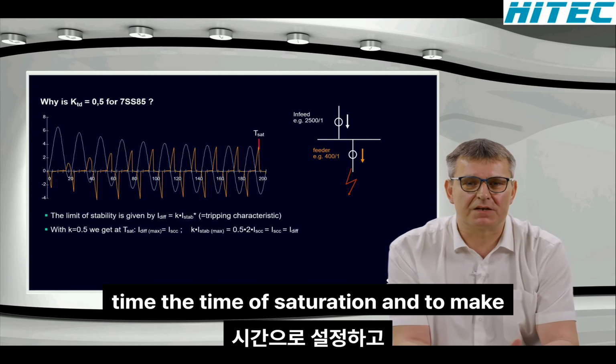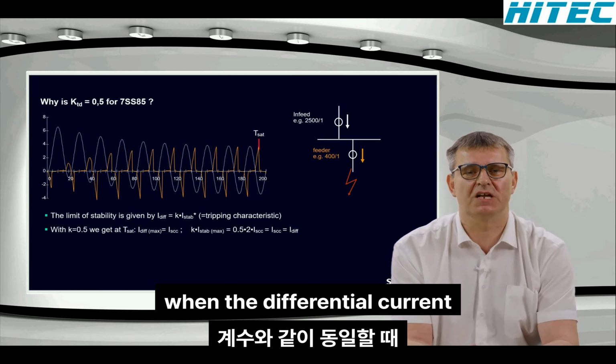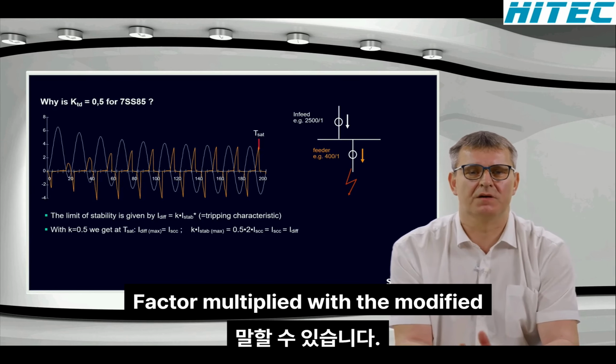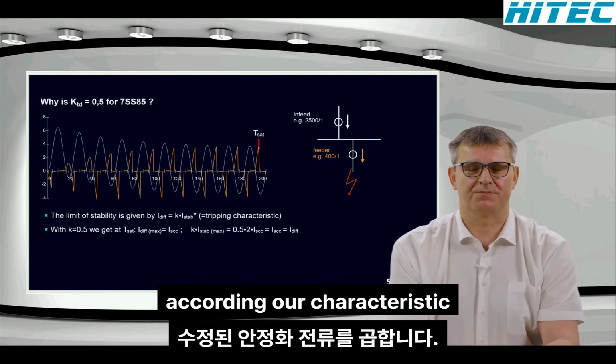And to make a rough calculation, we can say the limit of the stability is given when the differential current is the same as the stabilization factor multiplied with the modified stabilization current, according to our tripping characteristic.